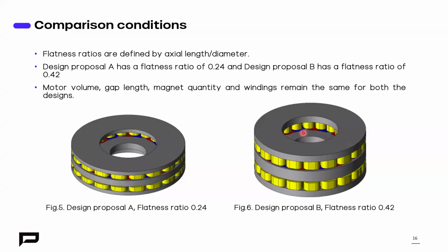How long does it take to solve for a 3D efficiency map? It depends on whether it is a partial model or a full model, and how many cores you are using. If it is an 8 core system and a partial model, maybe within 2 hours you can get your results. Any idea about simulation time, how many cores are required? A minimum of 6 to 8 core system is required for faster simulation.